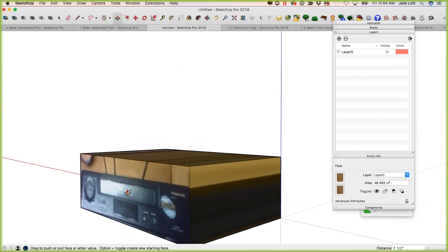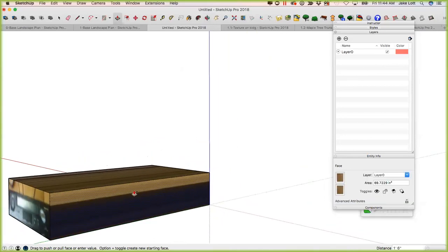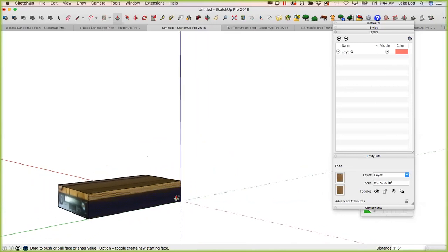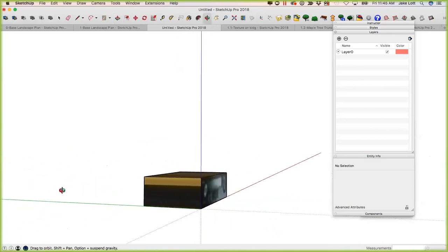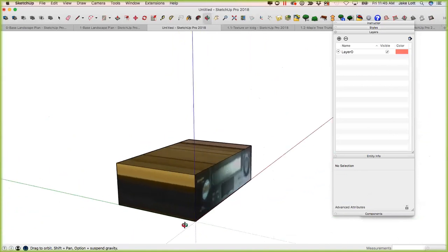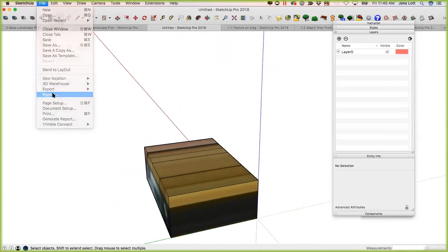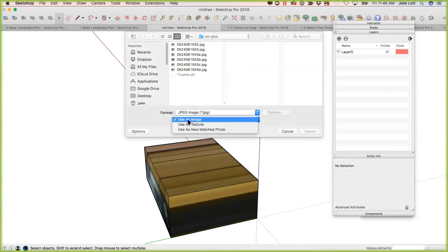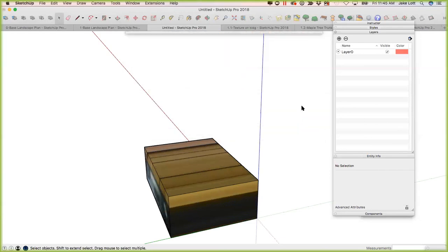Now it is right and ready for me, but obviously it is just flat. So we're going to grab the push-pull tool, and I'm going to hit Alt so that it gives me this option. So these are the kind of hidden options that we want to have. It leaves the face there, but it also pulls out this way. So we'll go ahead and go 1.5 feet. It's a pretty big one, huh? So before I make the final change, I can redo that. I can say 1 foot, it'll shrink in. Maybe it's 8 inches. So I can really start to fine tune what that actually does.